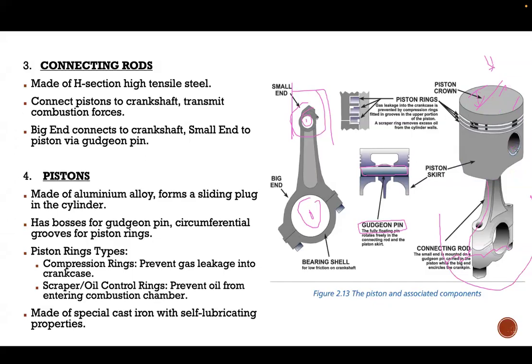The other part of your engine that we have to talk about is your piston rings. So piston rings are on the side, you can see these three silver colors, right? It's basically a seal that is kept to not let your fuel from the top seep into your oil system, or not let oil seep into your fuel. In both cases, you're going to have ill effects.